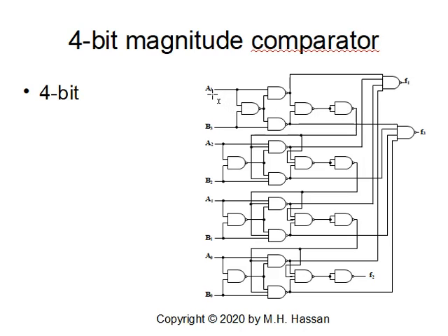So we have the inputs here, I hope you can see them: A3, B3, A2, B2, A1, B1, and A0, B0. So we start with the most significant bit. We verify that F23 is 1. We need to test the output of the second set of the 5 NAND gates. This has to be 1.